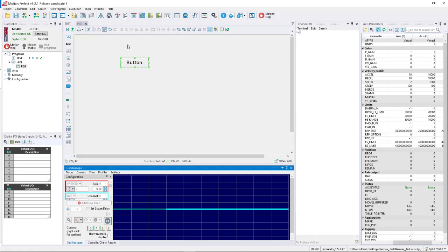Once you have the HMI hardware, and once you create a program as an HMI in Motion Perfect and download it into the HMI, it will send a compiled application to the HMI, which will run on the HMI by an existing application that we already installed on the HMI before supplying to the customers. So this application needs this compiled file from Motion Perfect to run on the HMI, and everything happens automatically. So you don't need to do anything special on the HMI.